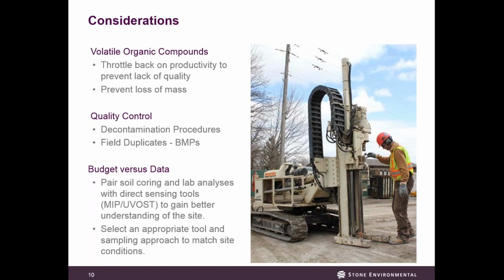The other consideration is that when you have a drilling company that's on a footage rate, or sometimes just wants to get home to see their girlfriends, there's an inherent productivity incentive for those guys. They're wanting to push it in as fast as they can and load you up with cores. So if you have 8 cores to log while they're just throwing them at you, they have 2 folks on the rig and you're there by yourself, it's not a good situation for quality. You can lose mass that way. The pore water will drain right out of those cores and you lose a lot of mass.